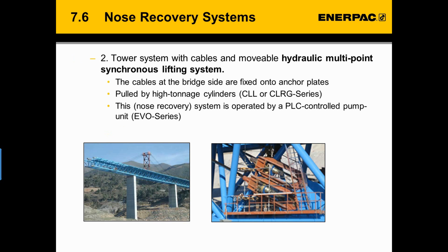A different nose recovery system makes use of a tower system and a movable hydraulic multi-point synchronous lifting system. Characteristics of these tower systems are that cables at the bridge side of the tower are fixed with anchor plates. The cables pull the nose up with high tonnage cylinders, CLL or CLRG, and the system is operated by a PLC controlled pump, as in the EVO system.